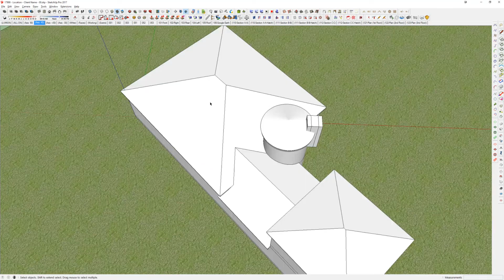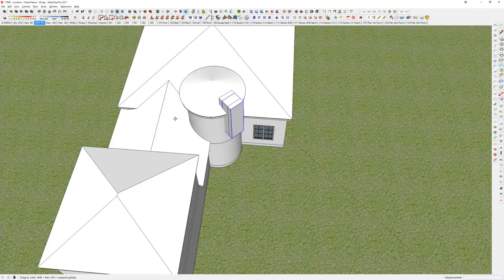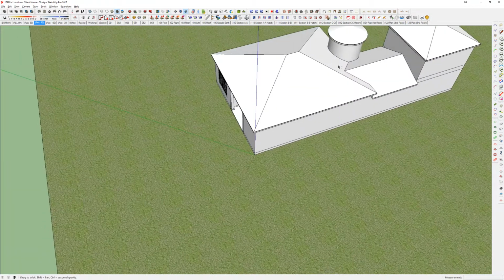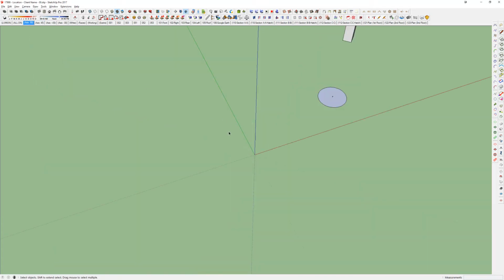And so before I could not move these on axes because they were on a 45. I've essentially changed the red axis to be orthogonal to my 45, if that makes sense. So there's also a plus 30. Let me hide these. So if I go back to my axis 90, which is my original, there's a plus 30, so it rotates at 30 degrees, or there's a minus 30, so it's kind of like I've just added in some of the more common ones, essentially minus 30, plus 30, and 45, as well as original 90.